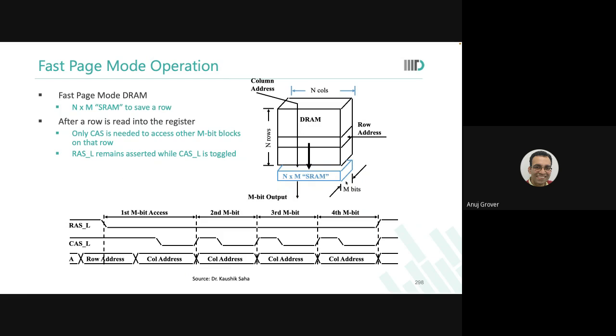So you see this N cross M SRAM that I talked about, at the bottom of the DRAM. Over here, we will put a small SRAM, which stores all the words in the intermediate duration, so that as the column addresses keep coming, the next words of the SRAM are made available. So you were asking how quickly I can give my next column address.